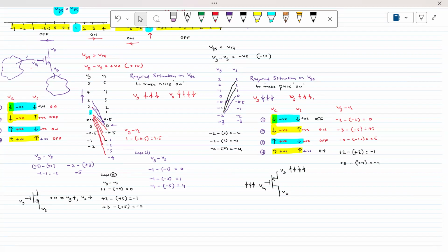So fundamentally, or blindly, you have to remember one important thing: for the NMOS transistor, the gate should be higher than the source potential, whereas for the PMOS transistor, the gate should be more negative than the source potential. That's what you have to remember. Okay, we stop here. Now afternoon we'll take another.